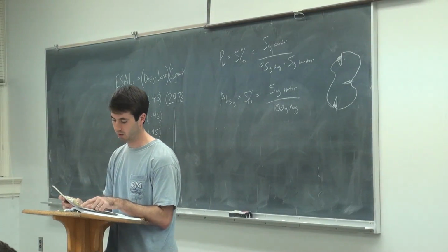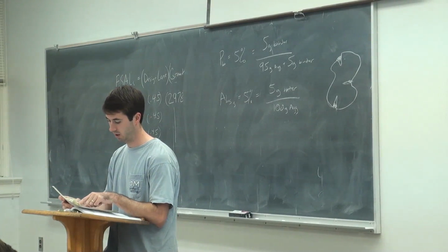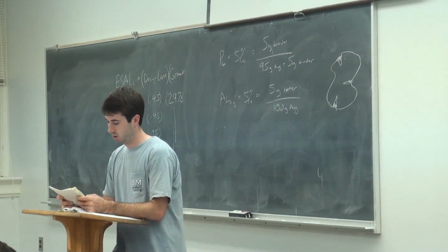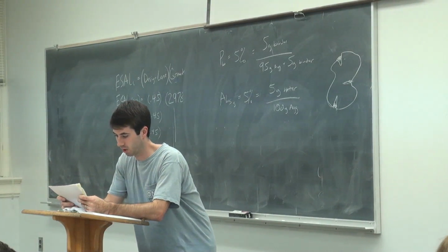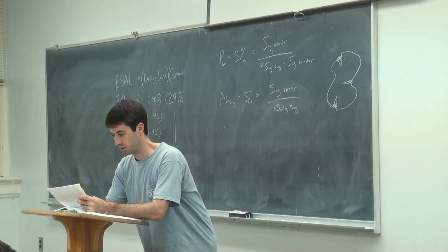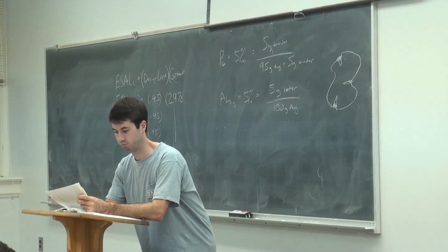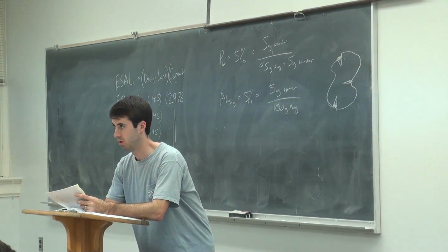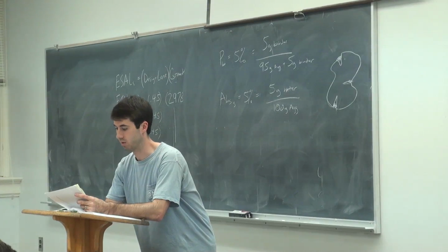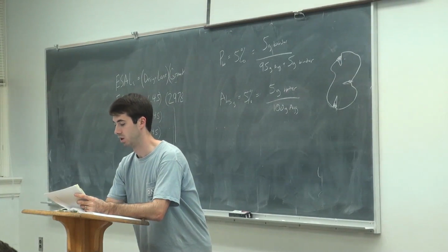But it's got a minimum value of 1 kPa at these temperatures. So if they ran this test at 52 degrees C and it was only 0.7 kPa, they would say it failed this test, we had to bump up the next temperature and run it again.